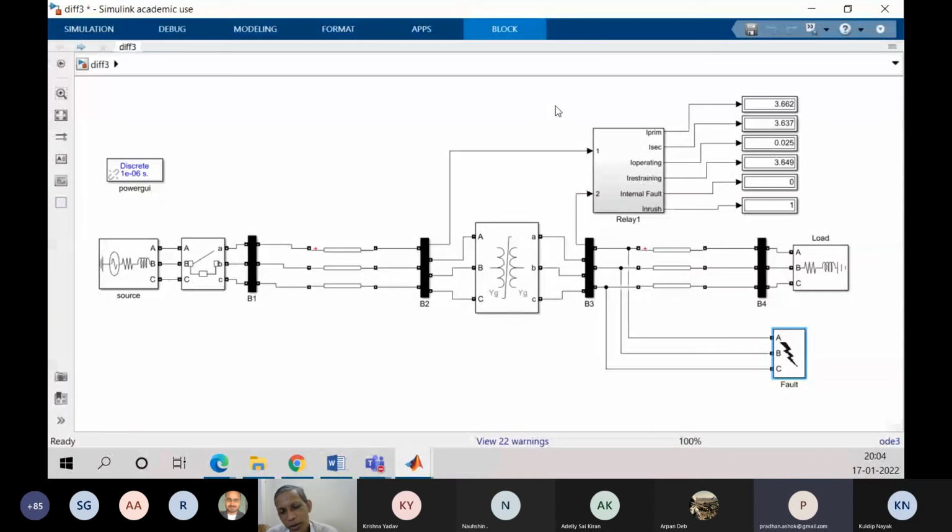So overall, what we discussed in today's lecture is that the transformer needs good, reliable protection, and a fuse is not adequate, an overcurrent relay is not adequate. Differential protection is pretty powerful, but simple differential, where the differential branch current becomes high, is also not adequate.